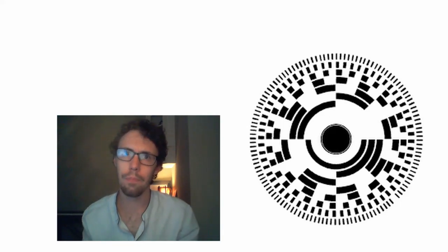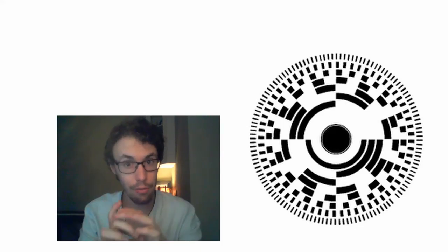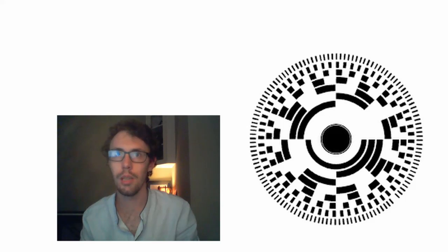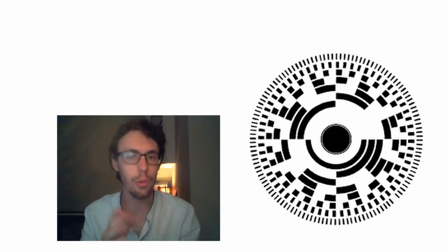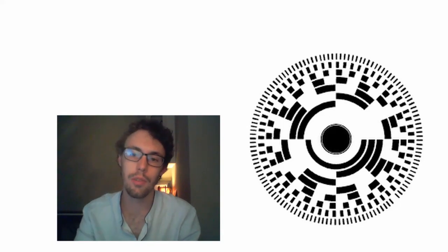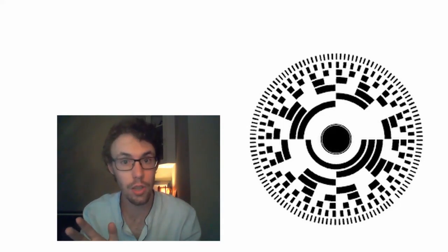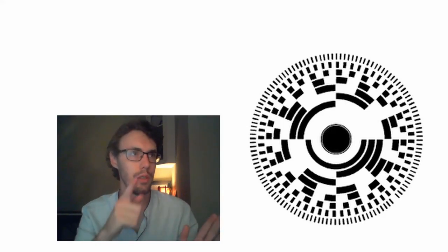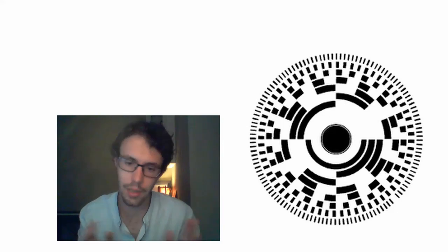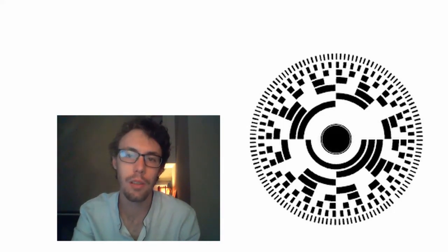So in other words, you only have 360 degrees, and if you want really fine resolution like we want, 0.02 degrees, you're going to have a lot of concentric circles and they become really expensive. The nice thing about these is that as soon as it starts up, it knows exactly where it is because all the little segments coincide with that position. But a much cheaper, better option for this is the incremental encoder.